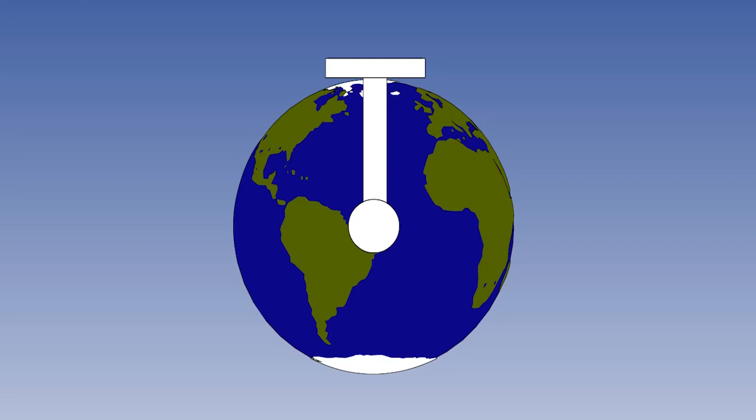When we discussed platform stabilization in an earlier lesson, we said that the V/R feedback loop could be likened to a large pendulum with a length equal to the Earth's radius, with the platform bolted on at right angles. The bob of the pendulum remains at the centre of the Earth. Then, as the aircraft travels, the circular motion of the rigid part of the pendulum keeps the platform level.